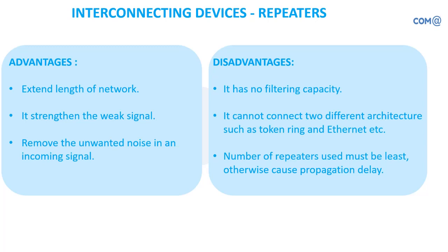The number of repeaters used should be small. Since it is amplifying, we cannot go for adding hundreds of repeaters. There should be some 5 or 6, less than 10. Otherwise, the purpose of having a repeater will be wasted.